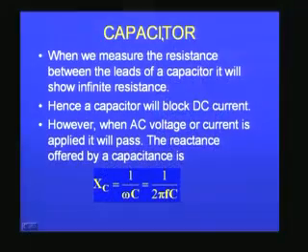So, if we measure the resistance of a capacitor, you can imagine the resistance in this case will have to be very large or infinity, because you have two plates, there is no electrical connection between them, and apart from that you have introduced a dielectric, either air or glass or mica, things like that, and therefore it will show infinite resistance.